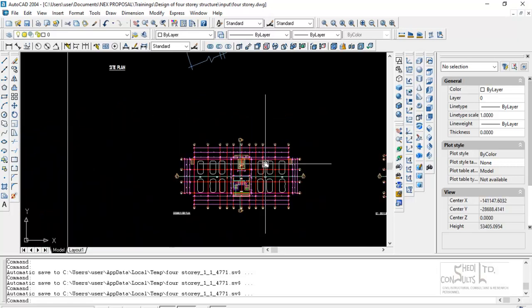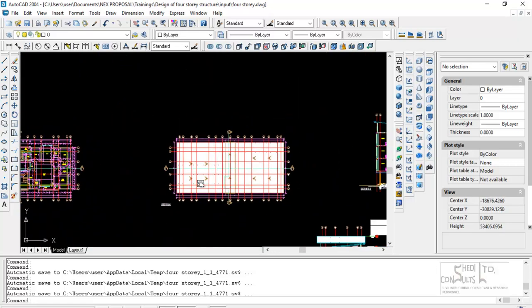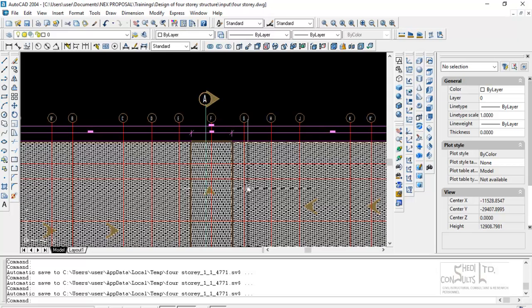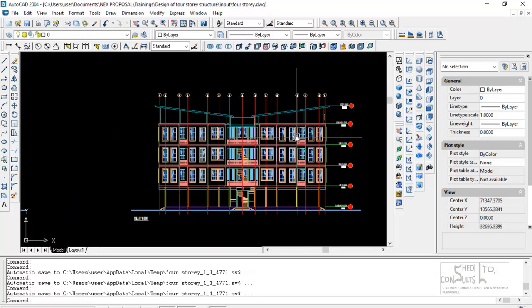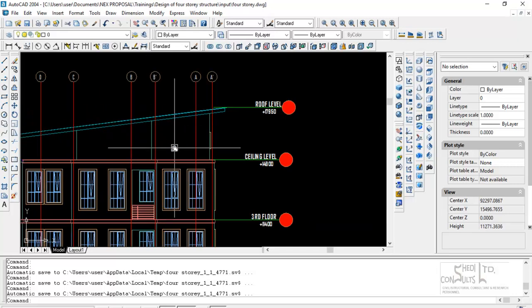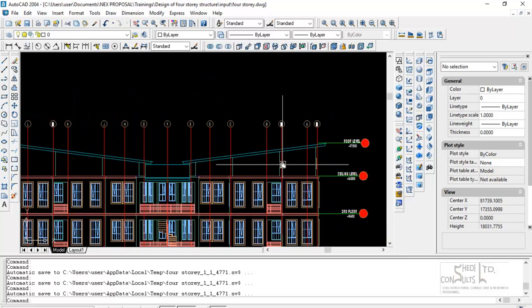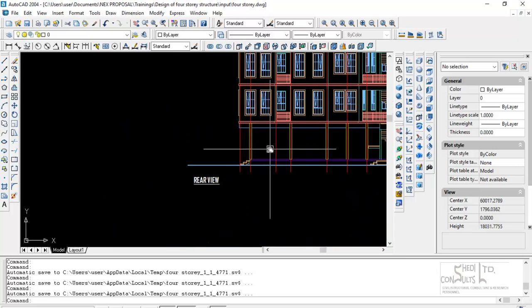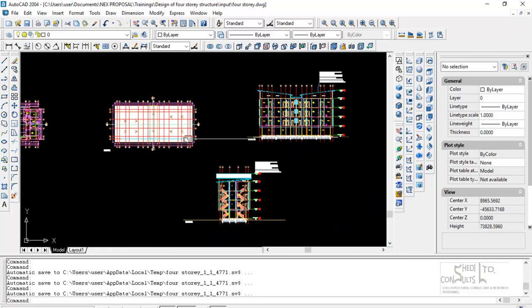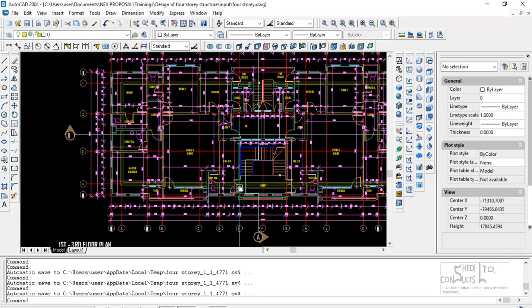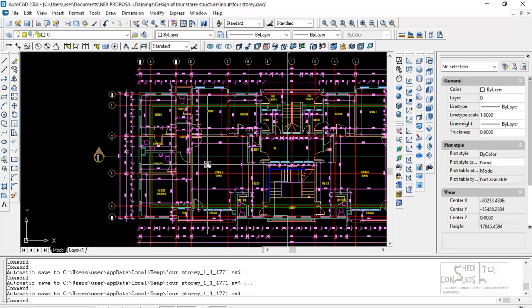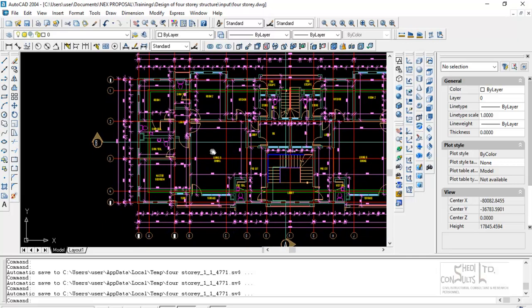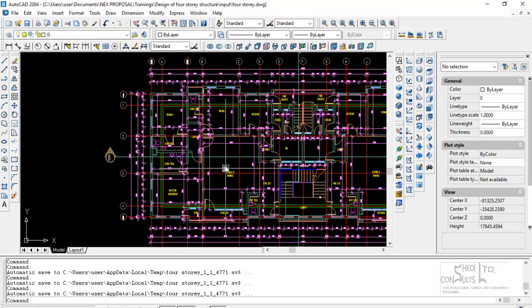hammer. It is used to drive down a split sampler. The number of blows used to drive it down the first 6 inches is not recorded, but the number of blows used to drive it further down by 12 inches is recorded as the blow count. That is the standard penetration test. The penetration tests you carry out on site are used to obtain crucial shear strength properties, to classify the type of soil present on site based on one of the classification systems, either the AASHTO classification system or the Unified Soil Classification System.